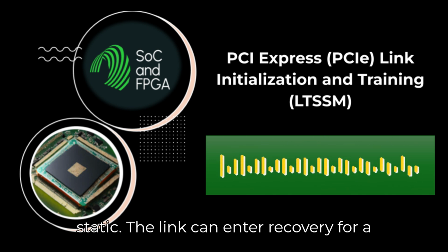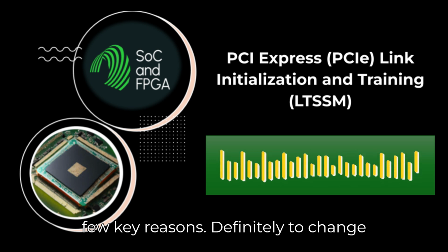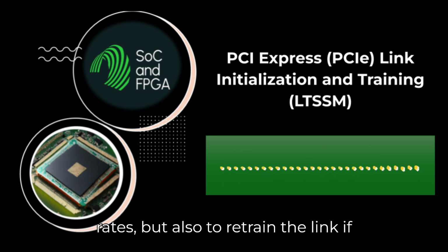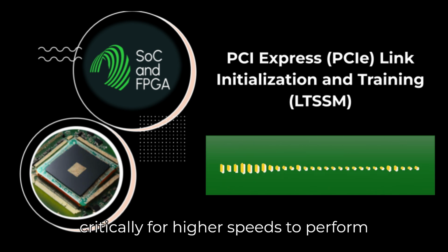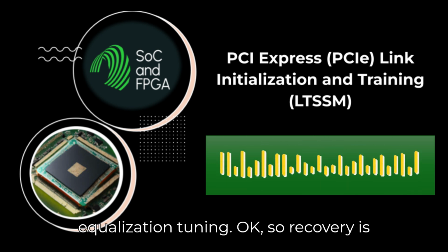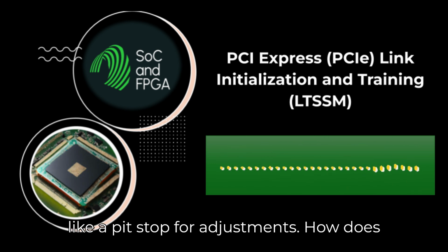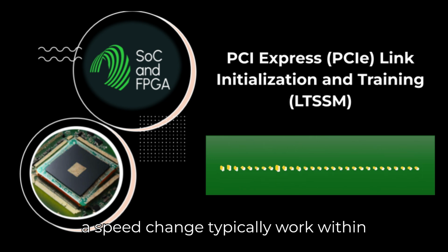L0 isn't necessarily static. The link can enter recovery for a few key reasons. Definitely to change speed if both devices support faster rates, but also to retrain the link if errors start creeping up in L0, or critically, for higher speeds, to perform equalization tuning. Okay, so recovery is like a pit stop for adjustments. How does a speed change typically work within recovery?